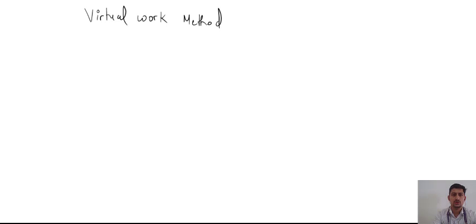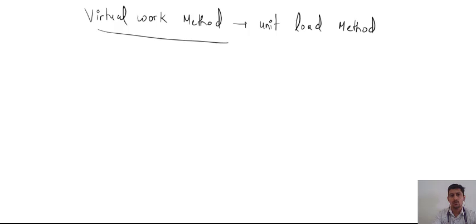Okay, so in this method, or you can say unit load method, virtual work, because in this we will be applying a load at that point for calculating the deflection which is not there, and we will be putting the value of that load equal to unit. So that is why we are also calling this method the unit load method.